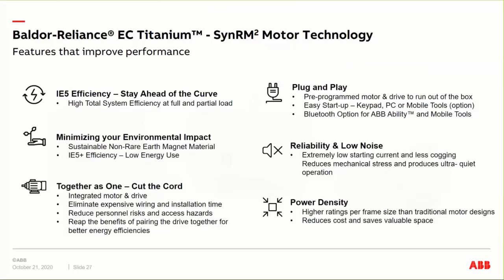non-rare earth ferrite materials. There are integrated drives and motors. I already talked about the benefit of the standalone drives, but you can get it with an integrated drive if you just want something that's drop-in, plug-and-play, and saves panel space. It has extremely low starting current because of the ferrites, and low noise. It's a very quiet running product, comparable to or lower than induction motors. So it'll be quiet in the system, and then there's power density for reduced size and weight in the system.